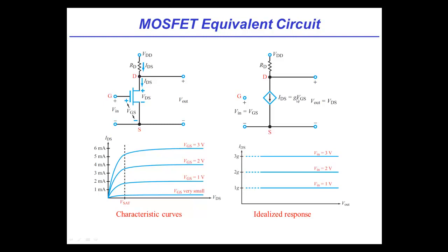So I've got my VGS voltage. Notice that this keys into what Vivek said: because there's an insulator, there's no connection, no resistive path, there's an infinite resistance between the VGS and anything on this side. In here there's a wire, and so maybe you think something's going on here, but there's nothing. This VGS, with nothing connected to the left, flows no current. If I were to put a resistor and a realistic voltage source there, there would be no current, so Vin would equal the source voltage exactly. And so the current IDS is just going to be G times VGS.